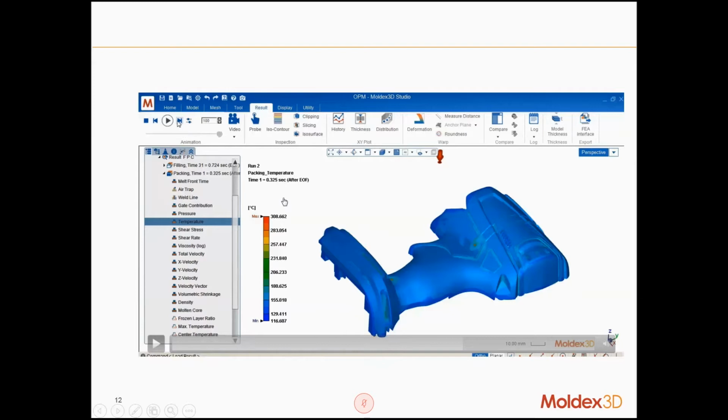But once we switch to the next time step, you can see the minima and maxima numbers changed. So it's very difficult to see anything just from these colors. But once we use this fixed range and we switch the time step, the range won't change anymore.